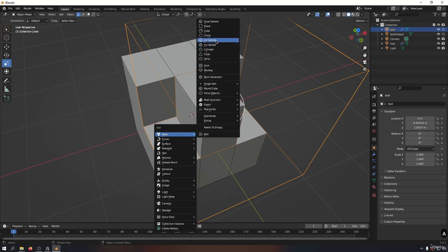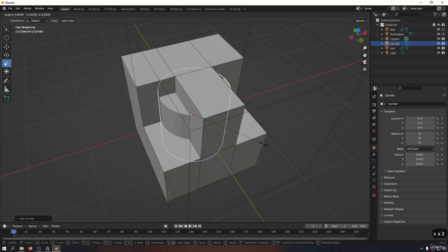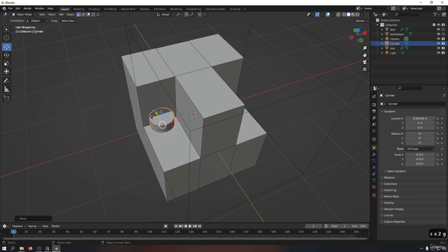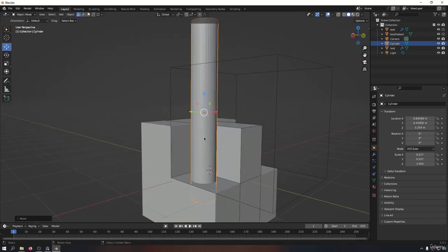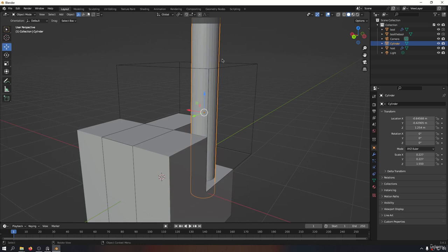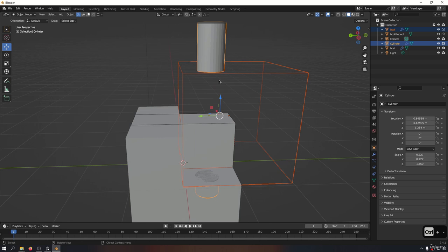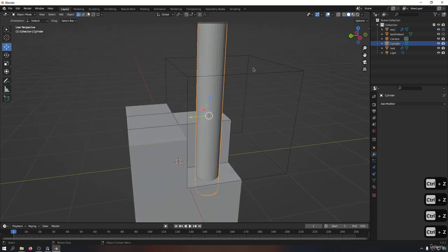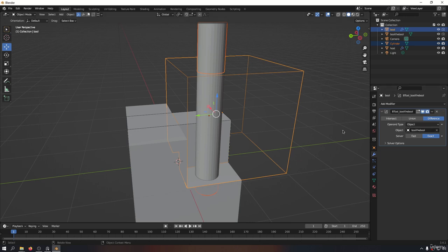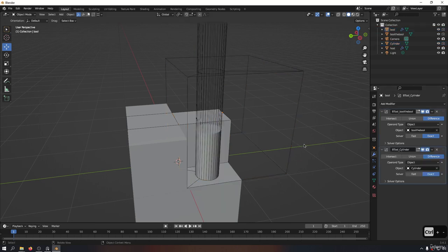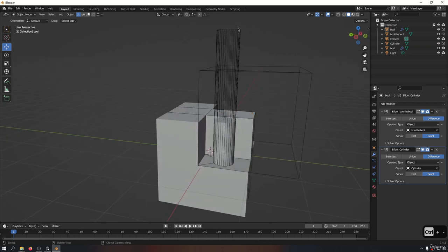I'm going to bring in a cylinder and let's bring it here. Now let's resize it a bit, and I'm going to take this and this one as the host piece. So now I'm going to Control minus. Looks like I've gone the wrong way. Let's take this one and this one as the active object. So now Control minus. So here you see it's cutting the piece.